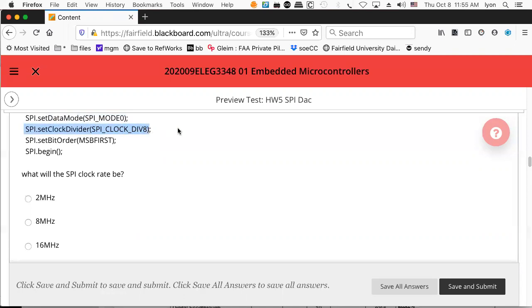And the question is, how do we know what to set the SPI clock to? And the answer is, we can't unless we know something about the device we're trying to drive. If the device can't go faster than 2 megahertz, then we better be careful about setting the SPI clock to div 8, because that's really the upper limit on the device, and you don't want to actually drive these things at the fastest rates they can handle.